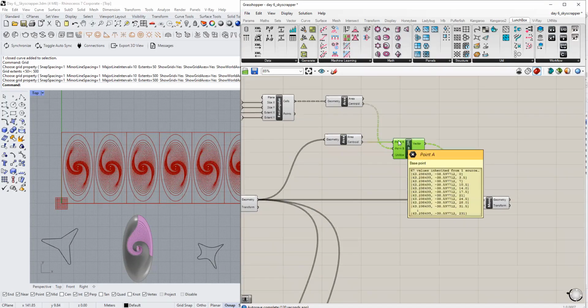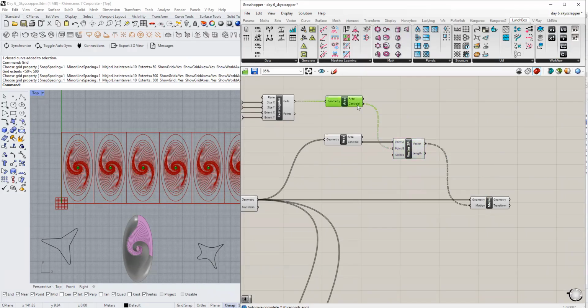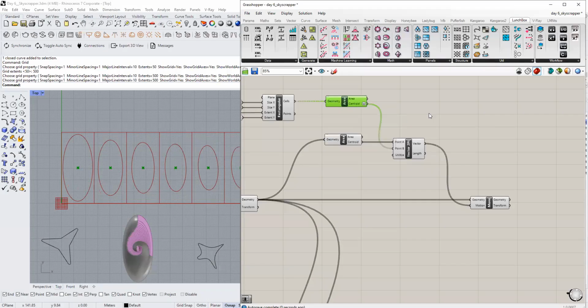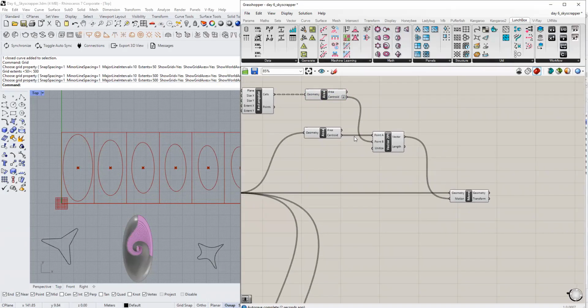Vector to point has correct set of inputs, but the output we have is wrong, which means this is where the problem is starting. Flatten it here or graft it, both of it will work perfectly fine. Just do either one of it and it should be sorted.